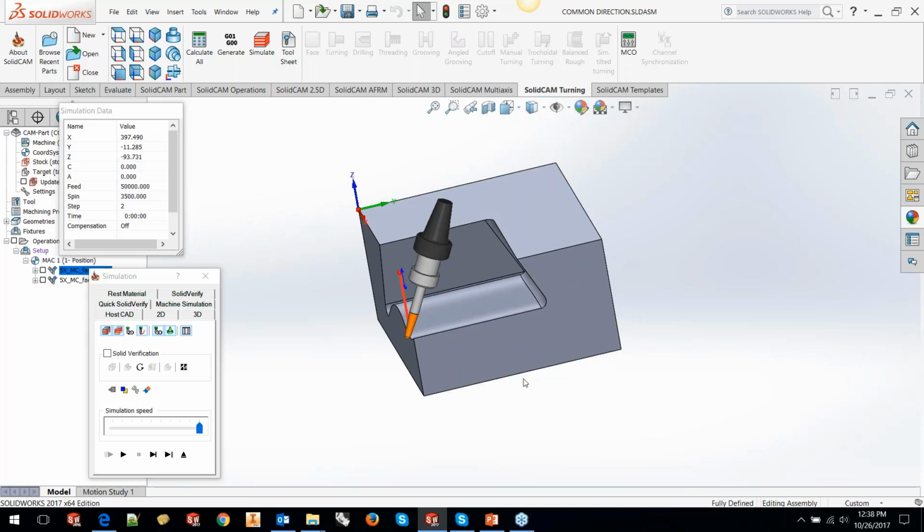because I have defined the tilt starting from a point, I don't want to create a gouge check situation where within a short span of travel it tries to tilt. So I want it to tilt uniformly. So I've tilted it through a point. What it basically does is, as it approaches that surface, because I've used a point, it's going to tilt itself and go into this area here.